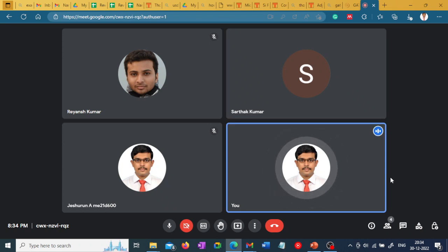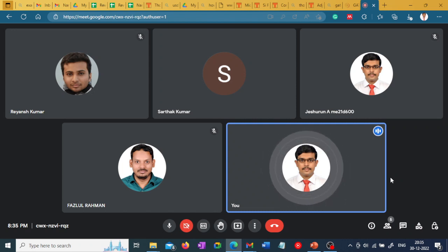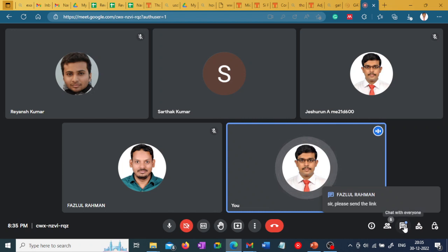No, actually, they both are the same only. Composite means, the thing is, matrix is your solvent element. Solvent means the majority of the composition, and the solute is the minority of the composition you are adding. For example, if you have metal matrix composite, the matrix, the majority element, will be metal. If it is ceramic matrix, the majority of the element will be ceramic, and the solute that you add can be metal or ceramic also. Usually if it is purely ceramic that you are adding to the ceramic matrix, it is called ceramic matrix composite. If you add a little bit of metal, then it's called CERMET, a combination of both.